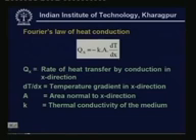As you know very well, the second law of thermodynamics says that heat transfer takes place spontaneously from a system at high temperature to a system at low temperature. That means dT by dx will always be negative as decided by the second law of thermodynamics. So, if you want to make Qx positive, you have to have this negative sign. So, the negative sign is a consequence of second law of thermodynamics.